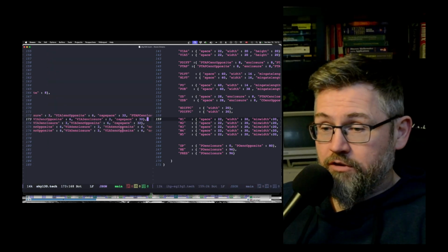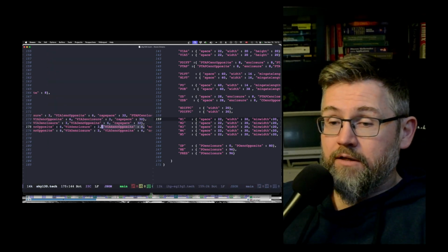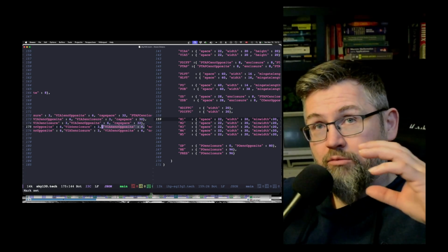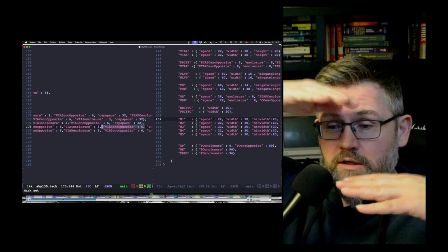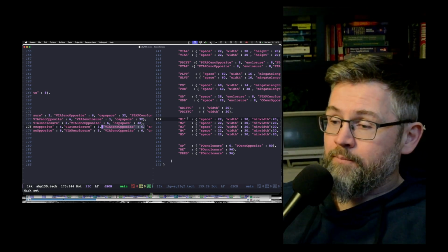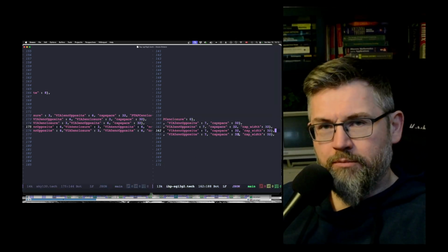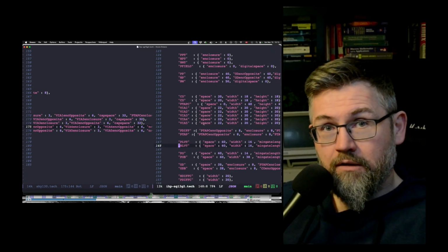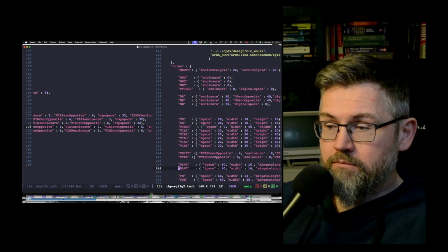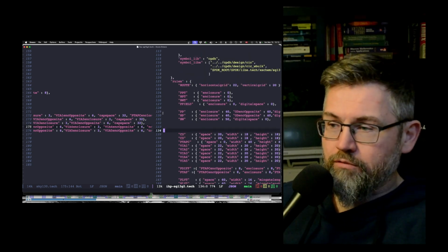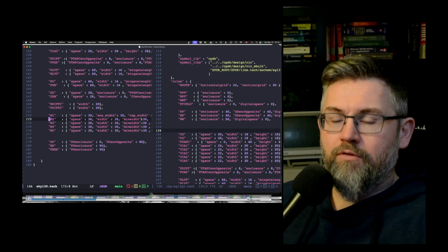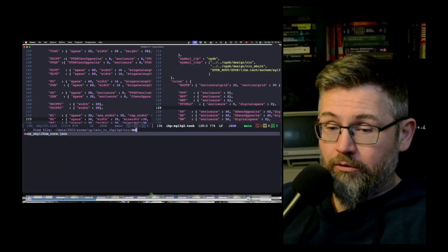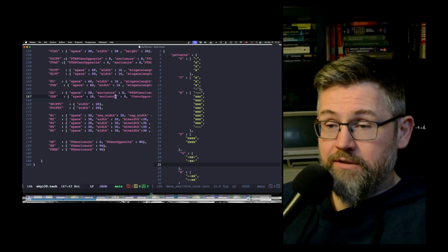and it has, for example, things like the fact that in most technologies you can have a via enclosure that needs to be longer on one side than on the other side, and things like that. And in the porting between technologies, quite a lot of the time is spent in this rule file to try and adapt to the same technology. And also a lot of time is spent on the transistor.